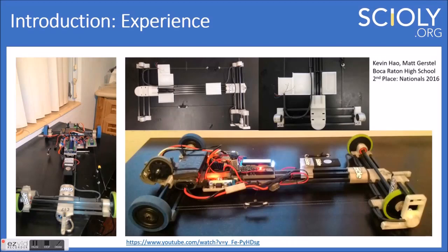We used 3 microcontrollers, 2 Arduino Unos, and 1 Nano. The 1 Nano was just to record the rotary encoder and just keep track of the rotations there. The encoder we used had a high output, I feel like it was 12 or 14 bits of digital output, which is a lot of information to keep track of.